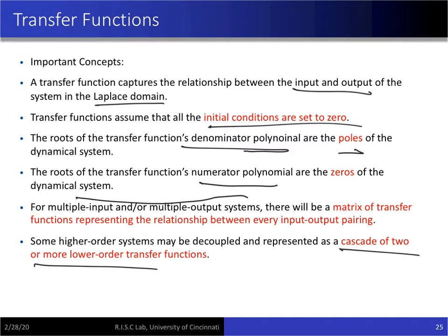Questions? Is there a benefit, besides it maybe making more sense, to splitting it up and decoupling it into multiple transfer functions versus just doing it all in one? So yes, I think there is a big benefit, because you will also realize when we do the solution of the second order transfer function, it's much simpler and the solutions are in closed form. You can tell when the solution will settle to the final value. What is the rise time? How much time does it take to go to the final value? How much error is there between the final value and the settled value? All these questions can be easily answered for a second order transfer function.